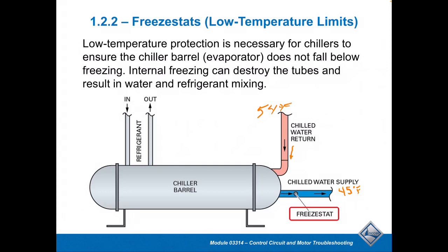So what would happen now is, let's say there's a strainer in the system, and of course the pump all of a sudden decides that it's not moving water. There would be other safeties that likely would try to handle that, but what if those safeties are not functioning? What we would have is a freeze thermostat that would look at the water temperature, usually very, very close to this particular chiller barrel. And so we may look at the outlet temp on there.